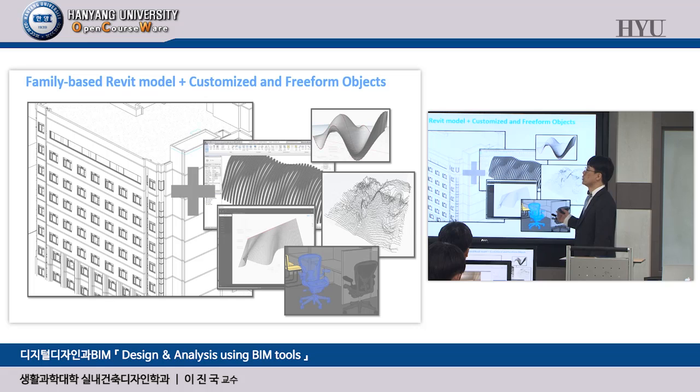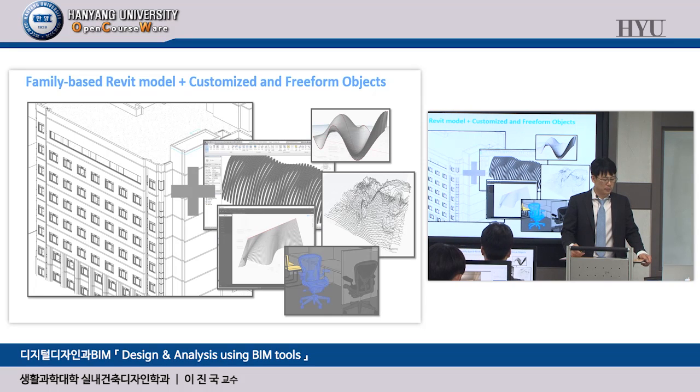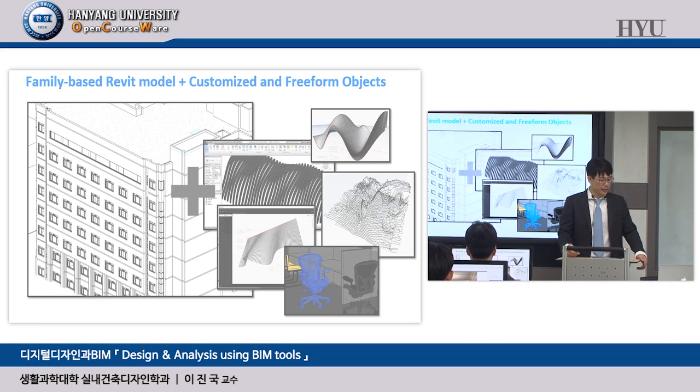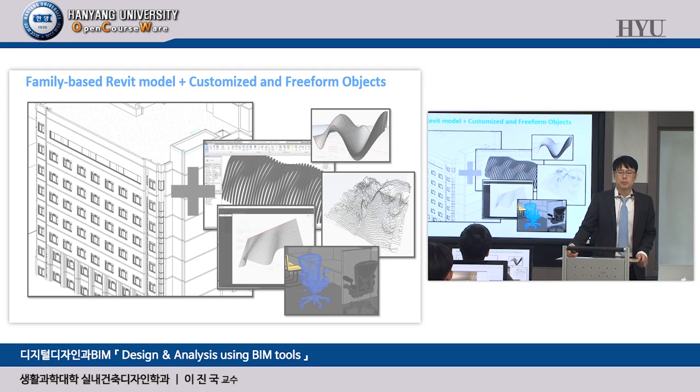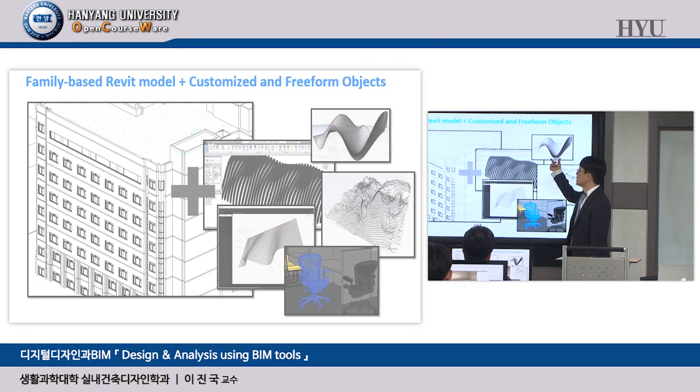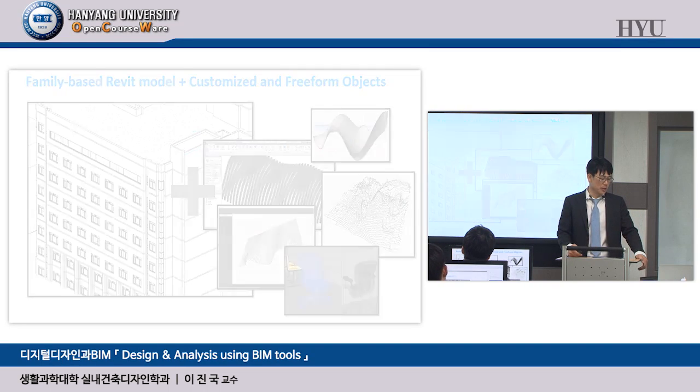That is why we are dealing with some external geometric handlers, how to use importing geometries or a Dynamo-based geometry making approach. So this is a very good and useful scenario for developing your project. Customized and freeform objects, any geometry can be handled this way. But for editable geometry, we need to know the family editor with Dynamo. That was my point.